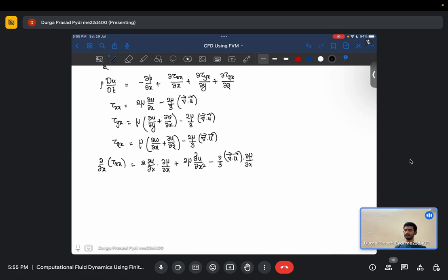So you see the challenge here when you are dealing with flows where your viscosity and density vary as a function of both space and time, then you need to know the precise functions of how they vary along space and time. So if you have a fluid whose viscosity is changing with respect to space, you need to actually know the values beforehand to be able to solve them. How we actually get that is a different problem.